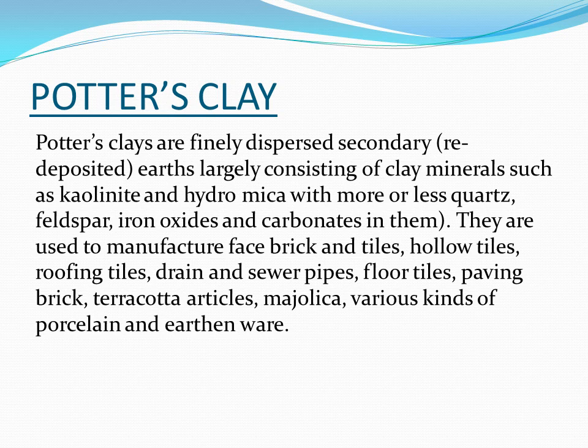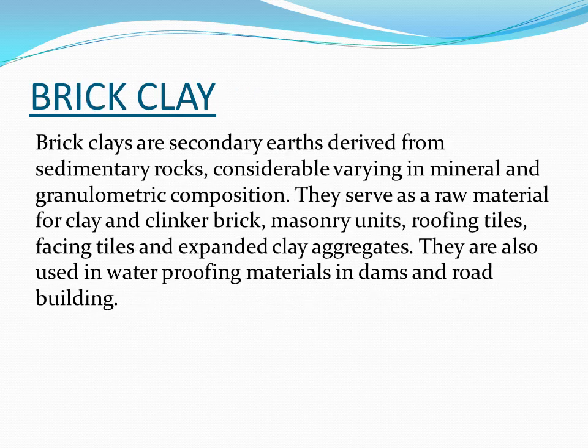It is deposited and then again redeposited. Potter's clay is used to manufacture face bricks and tiles, hollow tiles, roofing tiles, drain and sewer pipes, floor tiles, as a paving brick, terracotta articles, majolica, and various kinds of porcelain and earthenware.